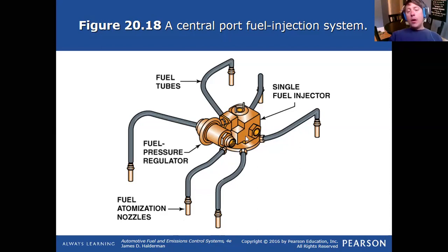And so that's the other way these things fail, is the lines would snap on them, and fuel pressure would literally just go straight into the crankcase, because these are located underneath the intake manifold. As you had the fuel pump on, it would just be spraying fuel straight into that unit. And if the unit was cracked, it would dump fuel right into the crankcase. And if it wasn't that the unit was cracked or the line was cracked, it would dump fuel straight out that injector nozzle right into the cylinder, and it would fill up the entire cylinder with fuel.